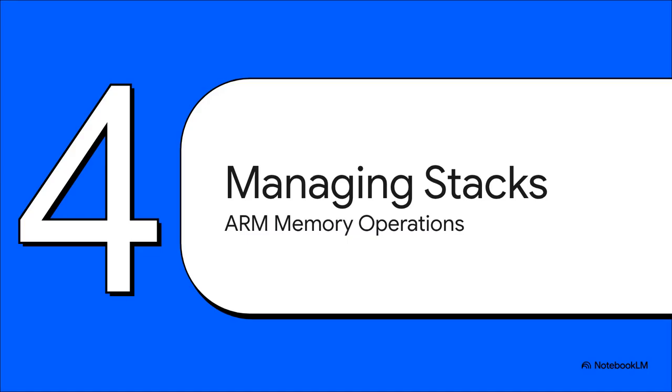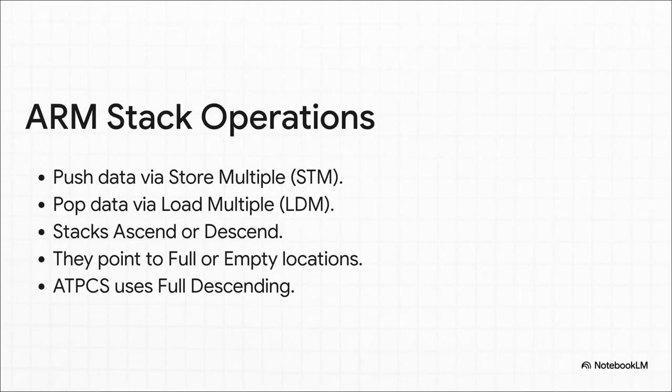Moving right along to Section 4, Managing Memory with Stacks. Now, to safely pause during those sudden hardware interrupts without losing its place, the processor relies heavily on memory management tools. Let's talk about stacks. Think of a stack exactly like, well, actually it's pretty much just like a stack of plates in a cafeteria. When an interrupt happens, the processor pushes the current state of its registers onto the stack. It does this rapidly using a store multiple instruction, or STM. When the interrupt is done, it just pops them back off using a load multiple instruction, or LDM.